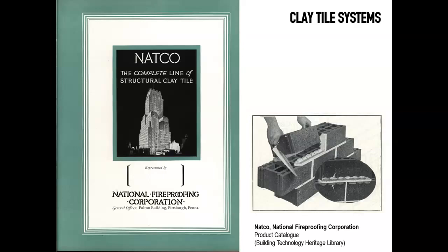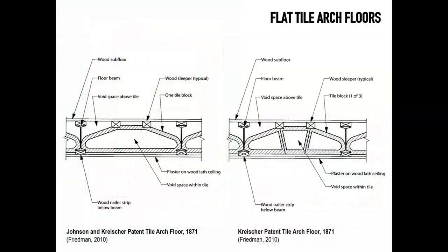So they are bricks that have been extruded and have chambers, and you can see here an example of these bricks that make these blocks lighter, but bigger as well. So they can allow you to build brick walls faster. They also have some capacity to be used in floor systems in particular, but they can be used also to fireproof steel columns, for example, or to make partition walls inside buildings that are fire resistant.